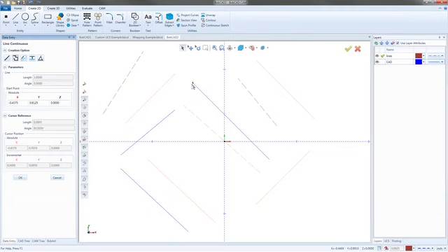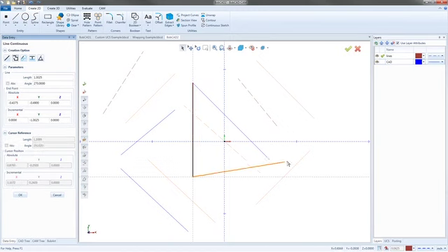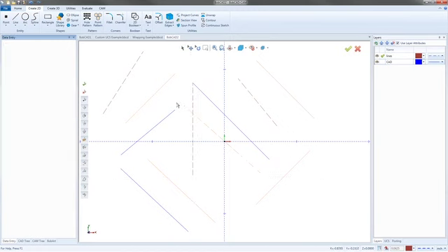So what's cool is as we sketch now, these lines will pop up. So if we want to sketch a perfectly straight line, we just have to wait for it to lock into position. So you just want to drag close to that 270-degree position or wherever you're going from. In this case, it'd be closest to that kind of 270-degree or straight down. And we'll see a preview pop up. And that previews that orange line. And then when I go ahead and click, we now have that line. And then I could cancel out. And there is that line. So it's a dotted line, just straight down. But we use our construction geometry for it.